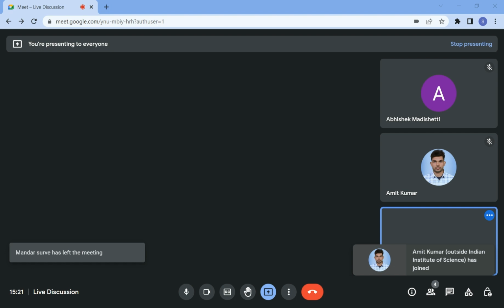And so this will be a circle, which is the locus of points with 45-degree inclination with respect to VP, and I have a line here which is the locus of all points B which are at 30 degrees with respect to the HP. So wherever these lines intersect, that is my actual projection of the line. So this was one locus with this as radius L cos 45.